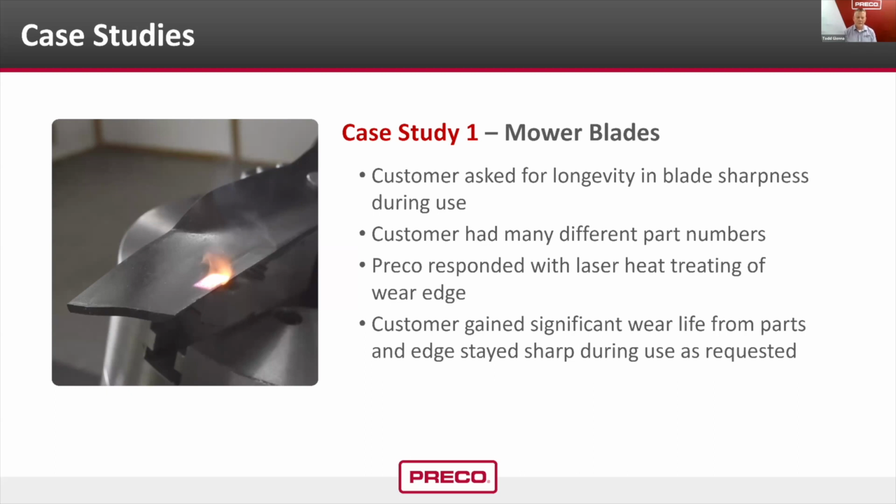And with all of these, you'll see that. And you'll also see that, like with this one, there are many part numbers throughout their series of blades, and they needed to reduce setup time. They didn't want to change tooling, so we made universal tooling to put various part numbers on. And with the controller, by changing the computer program, you could go from part to part with a CNC controller change rather than a tooling change or having things such as induction coils. So it was a very successful development and production program.